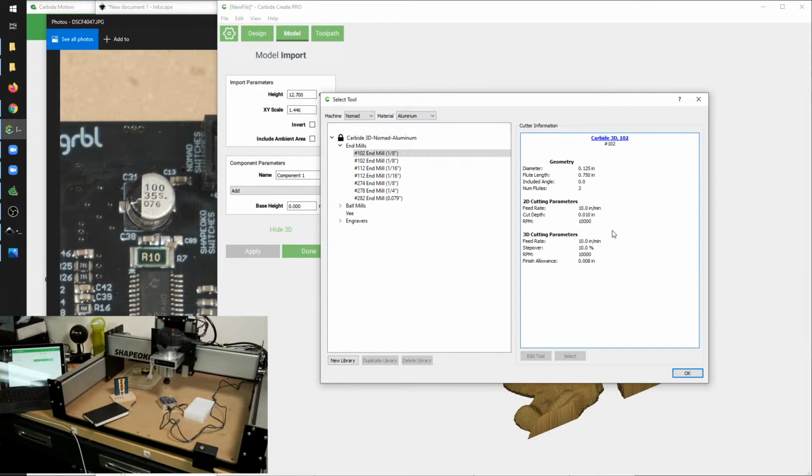There are different grades, alloys of aluminum. They all machine differently. Some are worse, which means you're going to have to take an even lighter cut. So instead of a 0.01 inch depth of cut, maybe a 0.007 or something. You sort of have to play around with it, but these should all be pretty safe to use. They're all relatively conservative. So feel free to try out some of these settings, and you can go more aggressively, less aggressively, depending on how you see fit, and go from there.